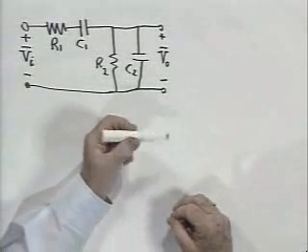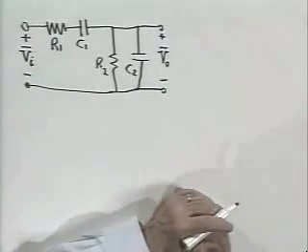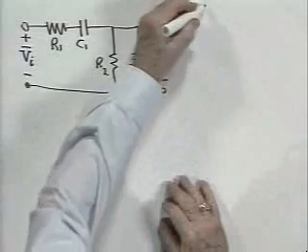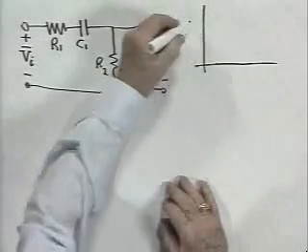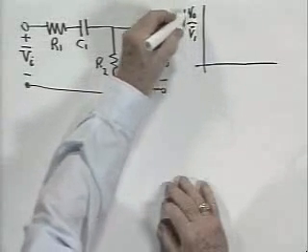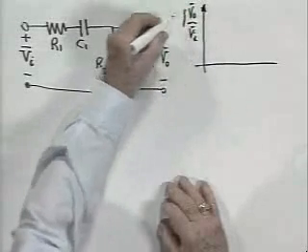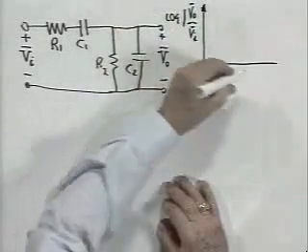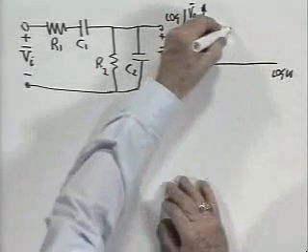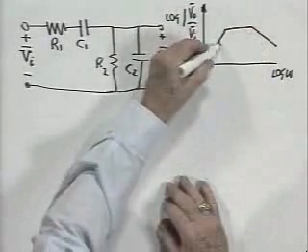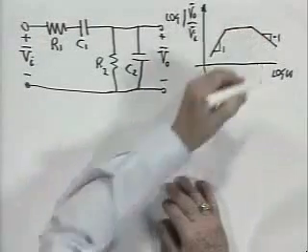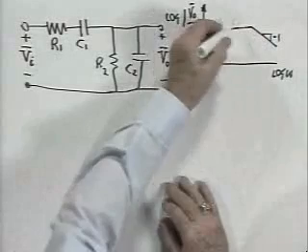So the Bode plot of such a circuit, with appropriate choice of the constants, is one which has, if I plot magnitude of V sub O over V sub I on a log scale versus log omega, a Bode plot which looks more or less like this. Falls off with a slope of 1 at low frequencies, falls off with a slope of -1 at high frequencies, and has some middle region in which it is relatively flat.